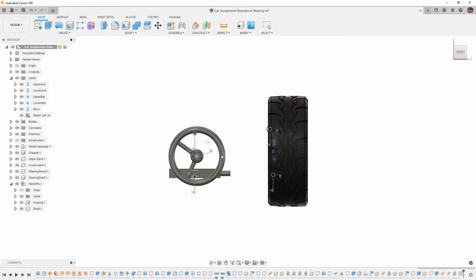Another tricky thing is the way that this wheel is set up, we're actually looking at it from the front. So this would be the front left wheel, driver's side if you're in the US. And what we're actually doing is we're steering it from the wrong direction. So we need to think about this. If we're turning the wheel to the right, this is going to be turning a point that's behind the steering axis, which means that it's going to be pulling it and the wheel will be turning to the left. So we just need to think about that conceptually.